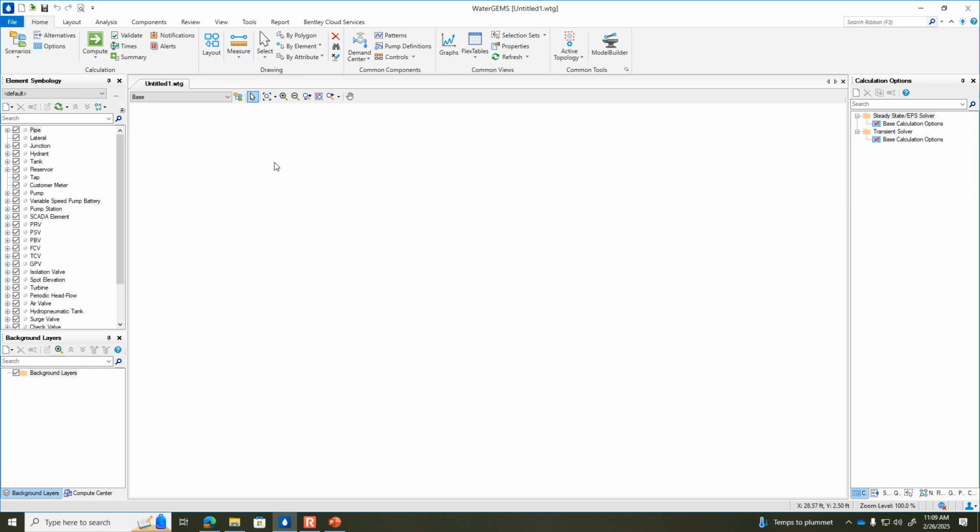So we're going to sketch out just a conceptual network. It's not to scale. We're just putting pipes in a representative way that's similar to what's on the paper here. So use this layout tool, and when you bring the cursor down into the project window, you can see that the cursor now is the tool for a junction. And the first thing I want to draw is a reservoir. You see here at junction A, it's showing that there's a reservoir with a water depth of 61.162 meters.